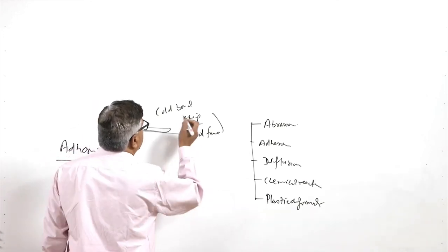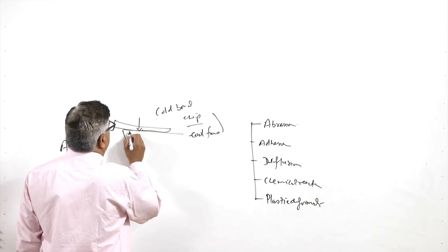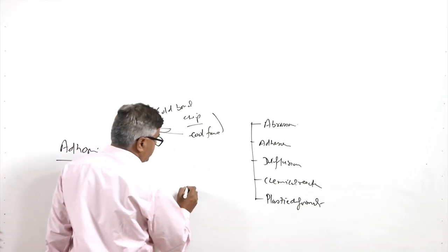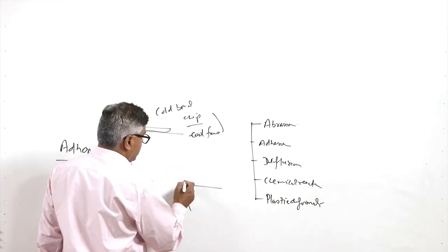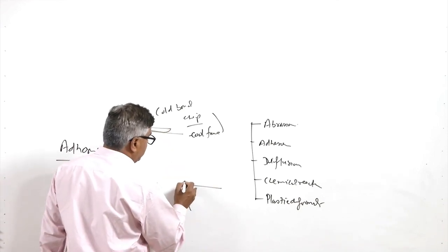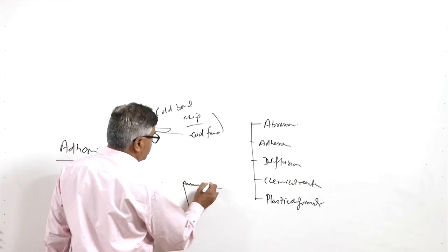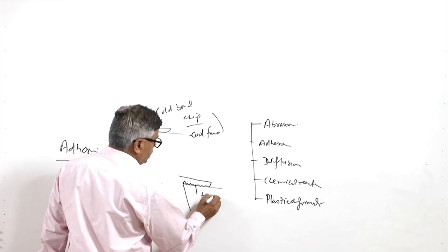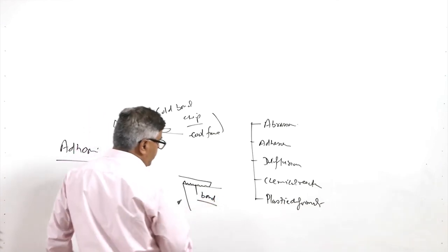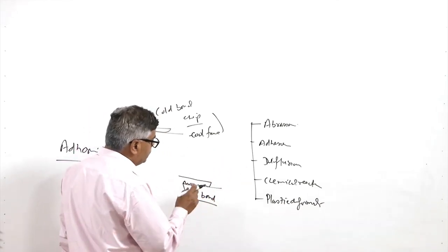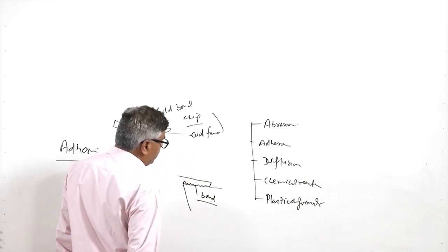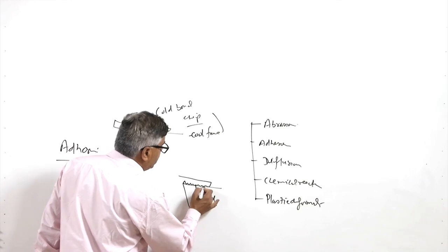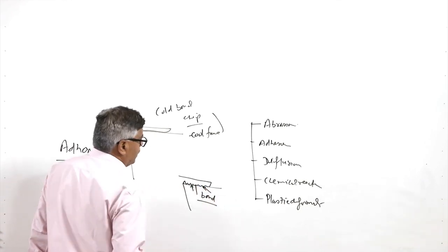This breaking of the bond causes the loss of material from the rake face of the tool. Say this is the face, and the chips slide under heavy pressure over it; they form cold bonds, and due to the continued motion of the chip over the face of the tool, a small piece of the material from the rake face will also be lost.